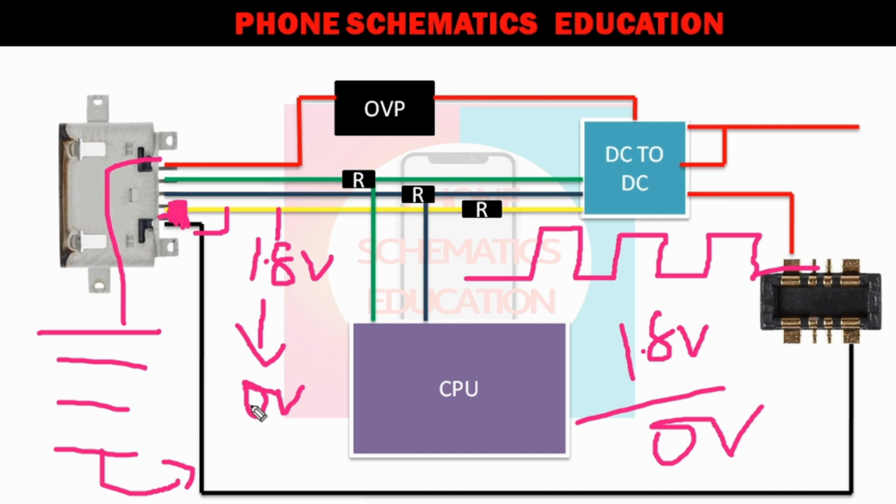Right? Now your IC senses: before connecting any device, here is a 1.8 value. Now something connects, so your voltage becomes ground or logic low. Before, logic high 1.8 volt; now here is 0 volt. So something is connected, mainly for OTG connections. So this IC activates the host mode. It means OTG mode.